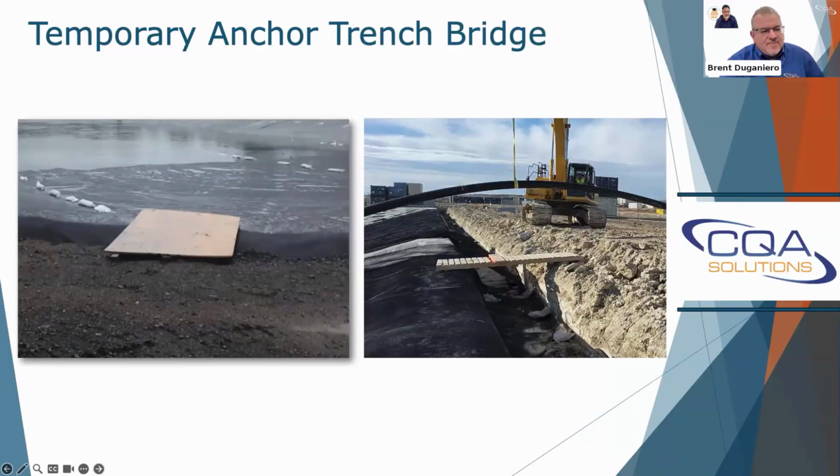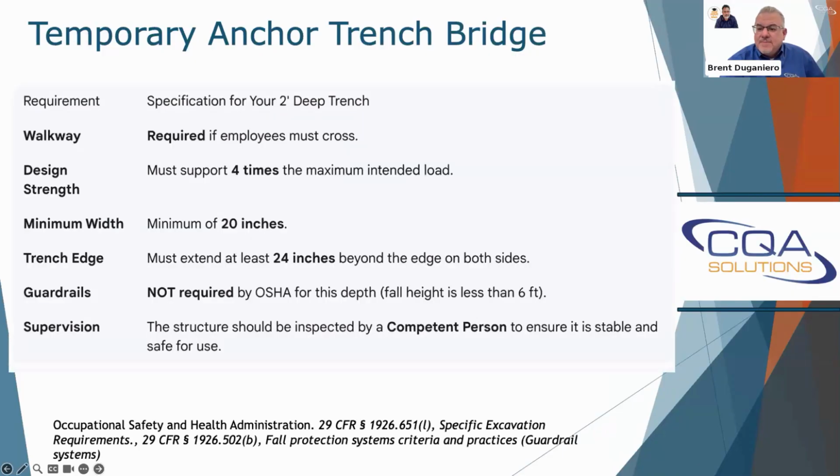But when we're using these temporary anchor trench bridges, there's some things that maybe we should consider. There's actually some OSHA regulations that we should consider. I said this is not an OSHA course, and it's really the furthest thing from it, but as reference, here's something that we can consider for these bridges. They got to support 4 times the maximum intended load. Okay, I'm not an engineer. I'm not designing these bridges, but that first one we looked at with the plywood, that one did not appear to be sufficient to hold the weight.